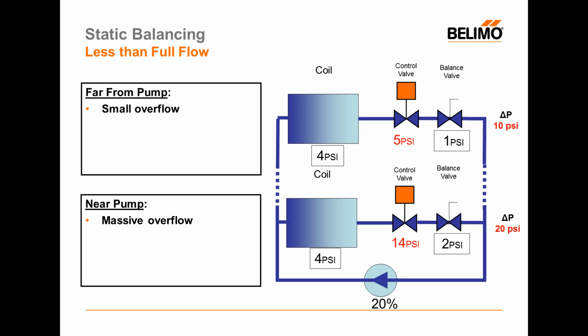So what happens in these types of zones is that we typically have trouble hitting our set points because we're overshooting them in both directions. And what it looks like is a control valve that's always hunting to hit the signal, and a discharge air temperature that's always a degree or 2 high or a degree or 2 low. And so these create unstable zones.